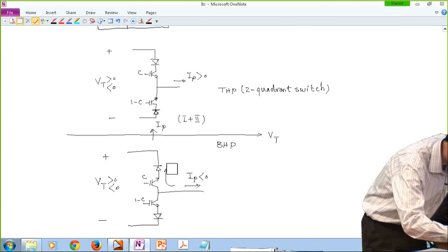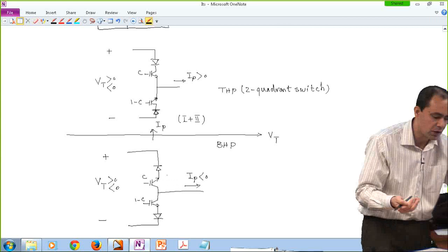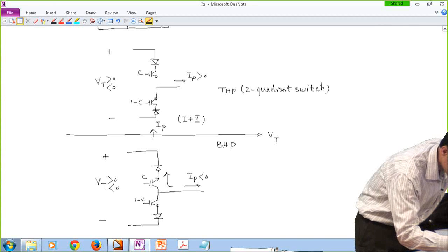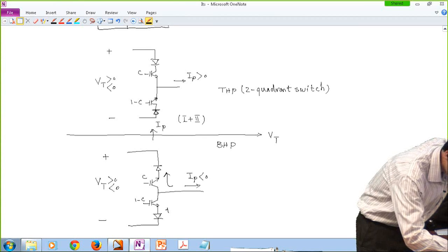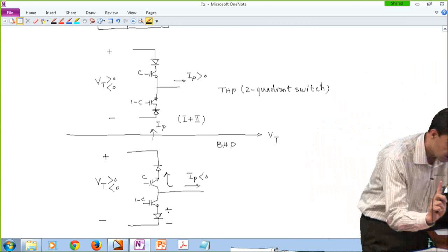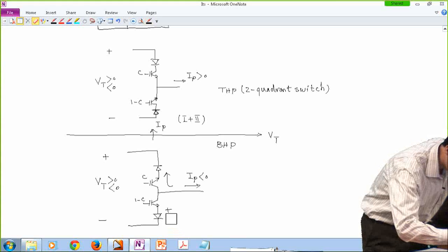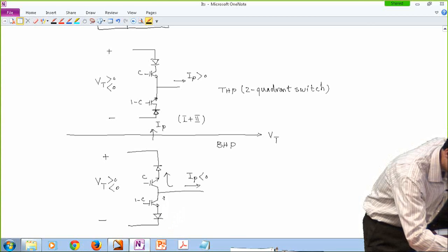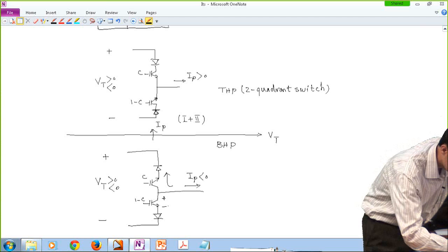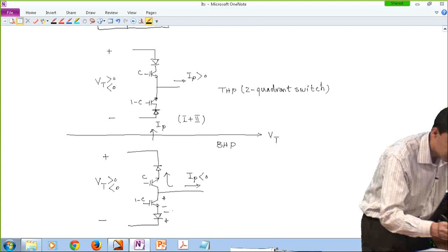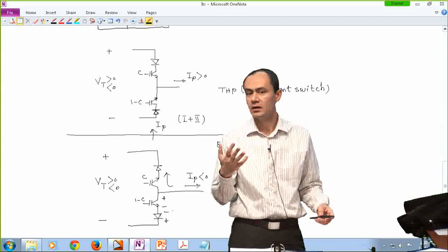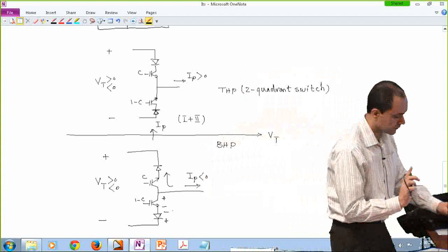So no problem there. In terms of blocking positive voltages, if we have a conduction going on over here, or the transistor is on, that positive voltage is being blocked by this diode basically. Okay? And I'm sorry, it's being blocked by this transistor. All right, and if the voltage is negative, that negative voltage is going to be blocked by this diode. So if the top throw is active, doesn't matter if the voltage is positive or negative, one of these elements is going to block that.